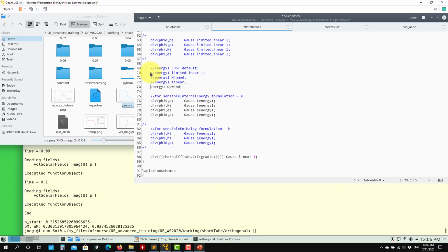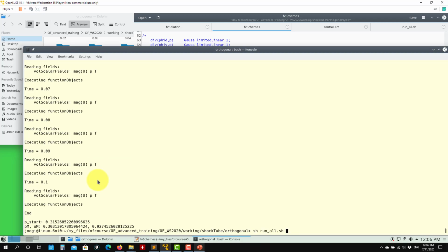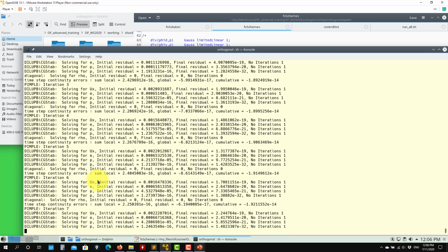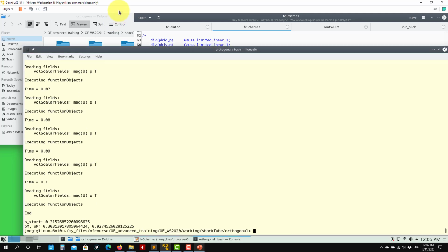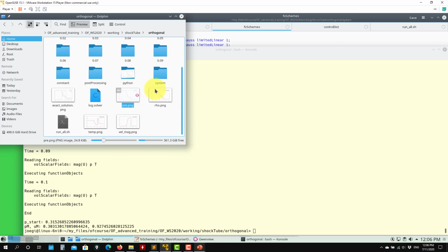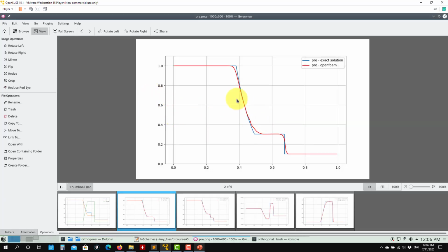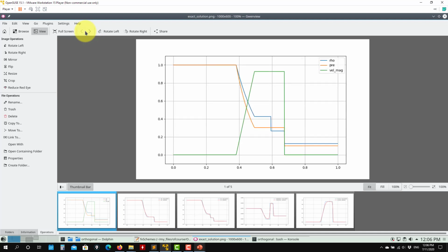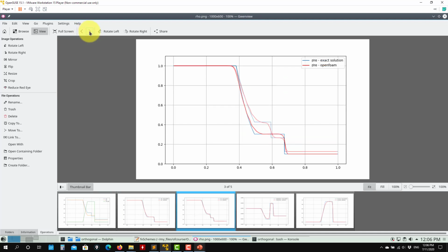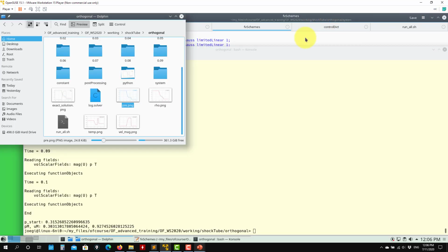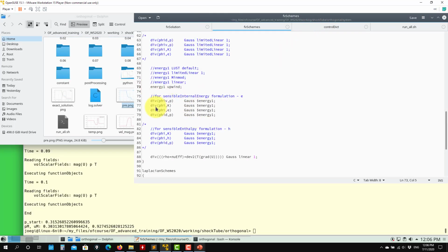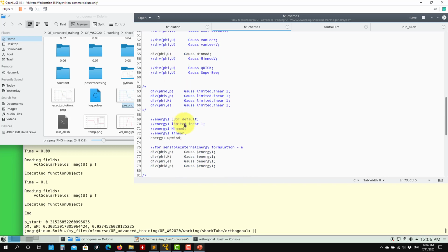So again, the same idea. I go here, upwind, highly diffusive. Let's see what happens. So it's putting all this upwind in all the equations related to the energy equation that we're solving. So we immediately see that it's more diffusive. So again, it's not recommended for energy to go and use upwind. Okay, it's less diffusive than for velocity, but you see there the diffusion.